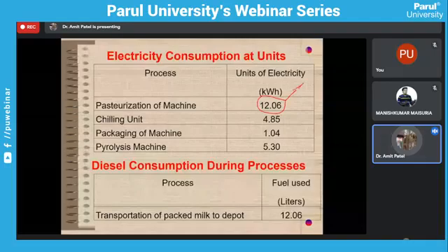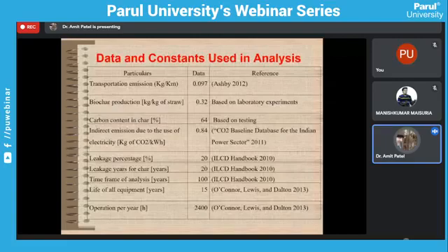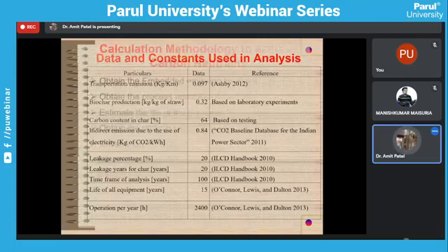So those are the component CO2 generation during the process. These process emission and fixed component will make a case, right? What we do is these numbers are then compared with some of the things we discussed, that biochar, right? In biochar, 0.32 kg per kg of straw we are generating biochar, and 64% of the carbon will be there in that biochar, a large number of carbon, and that is why we are after this biochar activity. Clear? So the calculation is very simple.